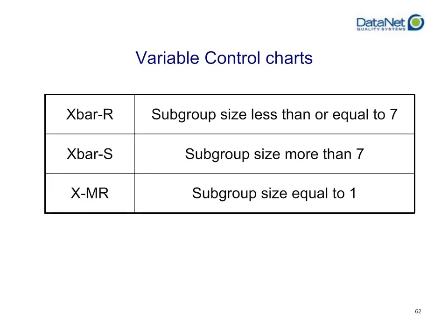Now, if you recall from the previous slide, we started talking about the different valid control charts that you could have for either variables or attributes. We will cover in a little more depth the different possible valid variable control charts, or at least the very common ones here. The Xbar and R chart is probably the most common chart. It is used anytime you have a subgroup size larger than 1. You tend to use it when the subgroup size is also smaller than or equal to 7.